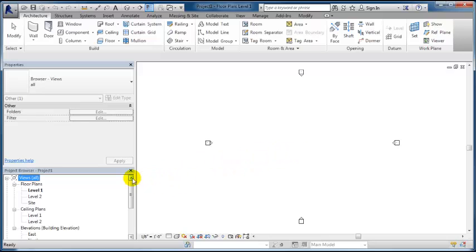The way that Revit works is you have a browser area here, which allows you to see your different levels. Levels are the number of floors that you have. They don't necessarily have to be just floors. They can be roof levels or mezzanine levels and things like that. You've got ceiling plans, or reflected ceiling plans for commercial projects. You have the elevations area here, and these are actually pointing to where our elevations will appear. When we create a model here, you'll see how that works.